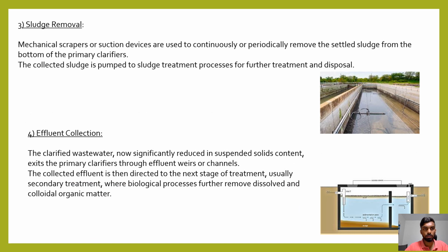The third process is sludge removal. Mechanical scrapers or suction devices are used continuously or periodically to remove the settled sludge from the bottom of the primary clarifiers.